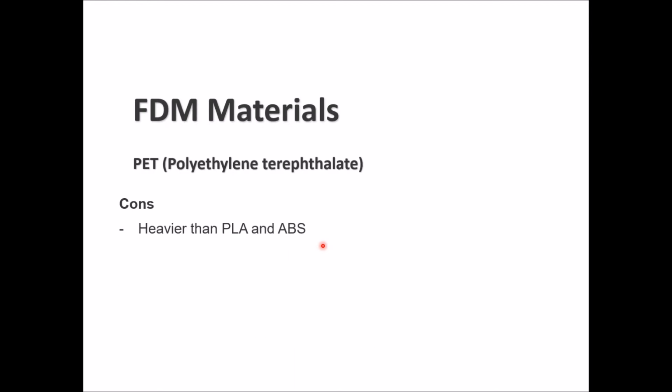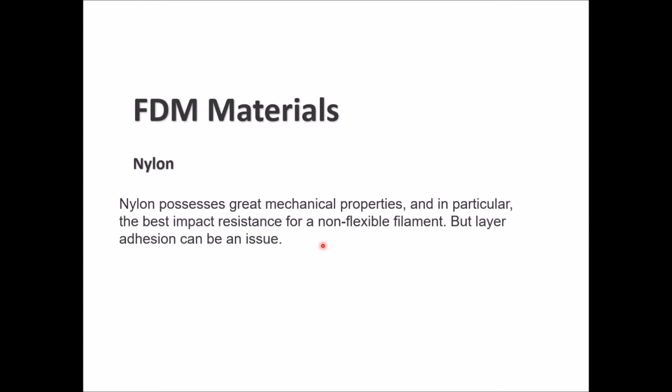Bad sides: it's considered heavier than PLA and ABS. If the weight of the part is a concern for you, then it's worthwhile designing with that in mind. A lot of 3D design software gives you the option to know the weight of the assembly or of the part. So it's worth assigning the PET material to the part and knowing what the weight of the part is compared to if it was printed with PLA or ABS, just to keep in mind that part.